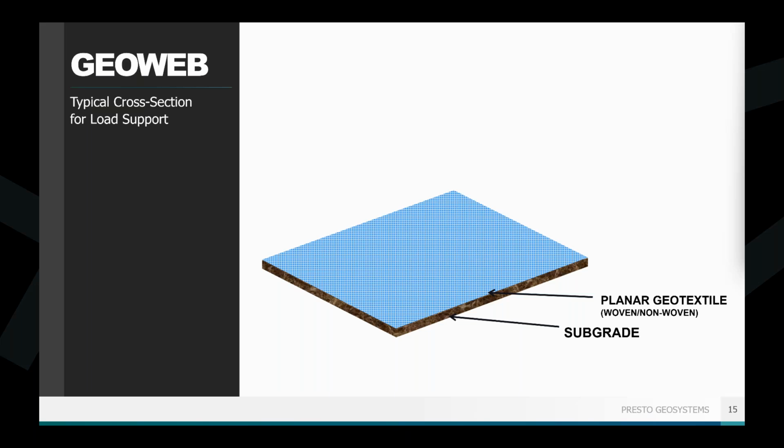And when we talk about woven geotextiles, I'm referring to what are called enhanced woven geotextiles, not slit tape wovens. And that is due to drainage. Slit tape wovens typically impede drainage. They don't allow water flow, or they significantly reduce the amount of water flow possible. Whereas enhanced woven geotextiles do allow for that free water movement.